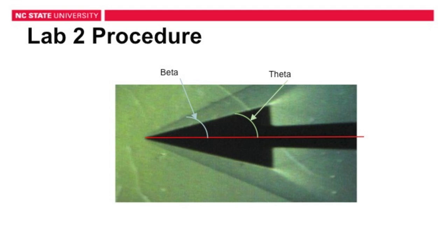In order to conduct Lab 2, the block setting was again changed from 2200 to 800, while the change in the angle of the shock over a 10-degree wedge was observed. These angles can then be directly used to determine the Mach number in the wind tunnel using the equation on the previous slide. Pictures such as the one seen here were taken during each test.